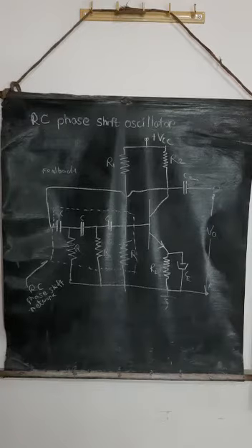When power is first applied to the circuit, base current suddenly jumps from 0 to the initial bias value. The change is amplified by the transistor and fed back again to the base through the RC phase shift network. This results in further increase in collector current. This action is utilized to sustain the cycle of variations in collector current between saturation and cutoff values.